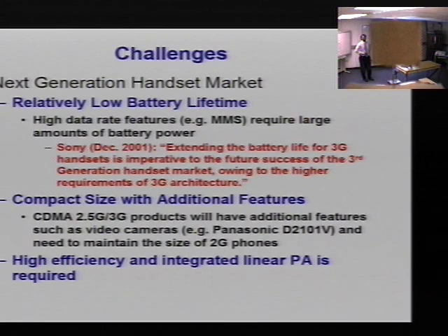It depends on the data rate, your bit error rate and your data rate. As long as you're willing to compromise a little bit on that, sure, a solution exists. At 5 gig for OFDM, I don't know if silicon is the answer yet. For wideband CDMA, if you give me a little bit of room on meeting over a number of frames, that might happen, but it's very hard dynamically to meet those types